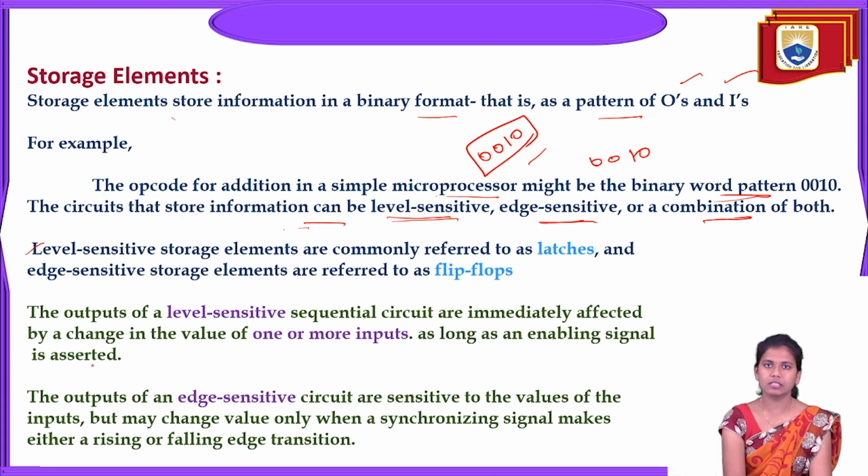Coming to level sensitive, what is it? Level sensitive storage elements are commonly referred to as latches. As discussed in the earlier statement, latches and flip-flops come under level sensitive or edge sensitive signal processing. Level sensitive storage elements are usually considered latches, and edge sensitive storage elements are considered flip-flops.